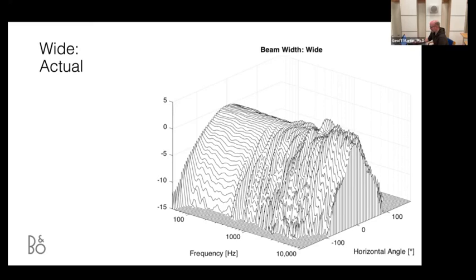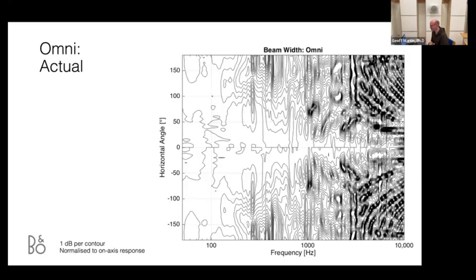One thing to consider with both of these cases, both the narrow case and the wide case, is that we're using a lot of energy fed into the amplifiers to cancel sound in some direction. In both cases, we're canceling sound in the rear of the speaker. In the narrow mode, we're also canceling quite heavily to the sides. And therefore, in both of those cases, what you have is a speaker that's not very good if you're throwing a party. And so what we made was a third directivity, which we called omni mode.